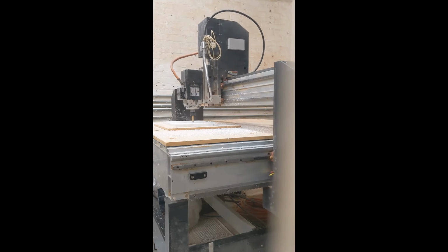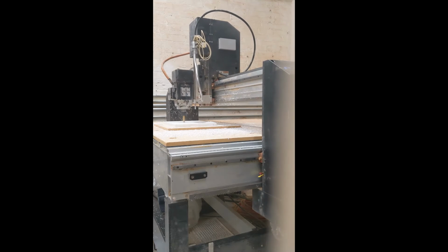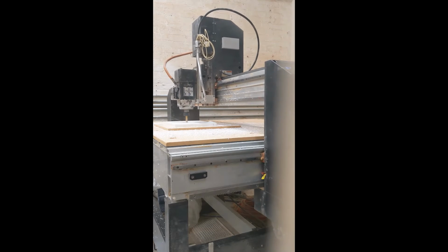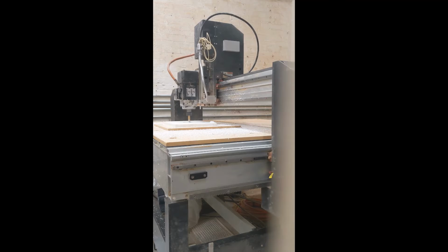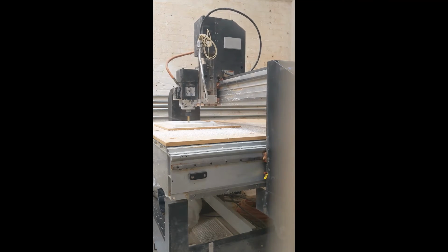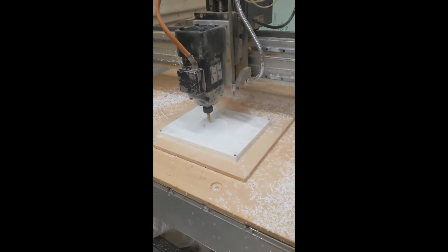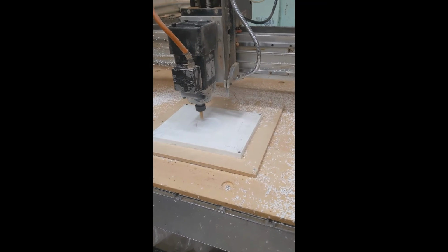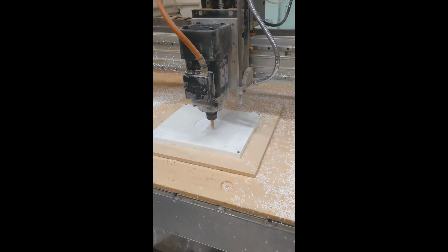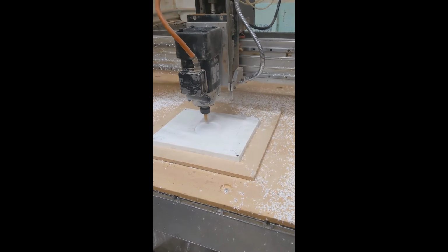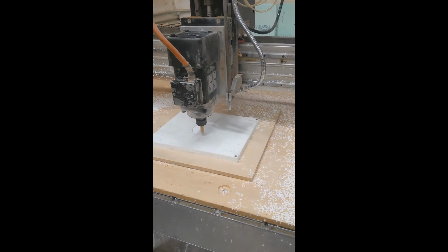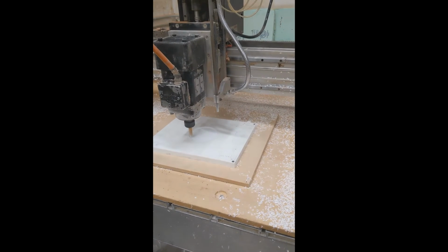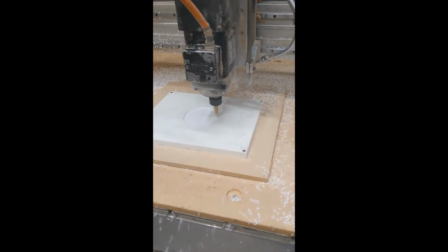If you're looking online in cookbooks or something that some crazy machinist in the dark corners of the web said was correct, you're just taking someone's word for it, and your material might be different, or temperature, who knows. So just listen to how the machine sounds, and you'll be much better off, and creep up on the final feeds and speeds. If you're going to be doing a production part or something, you're going to want things as fast as you can get them, but just start slow.